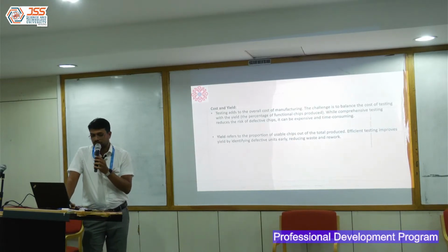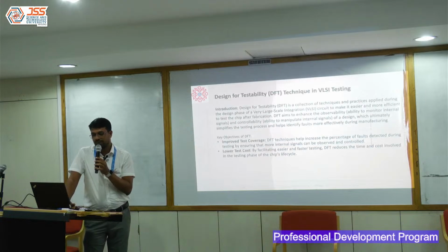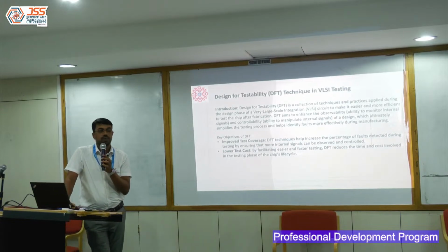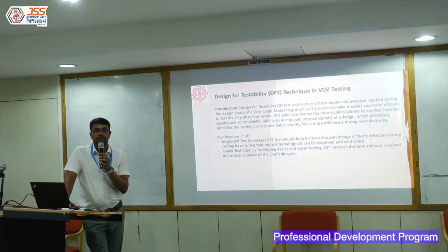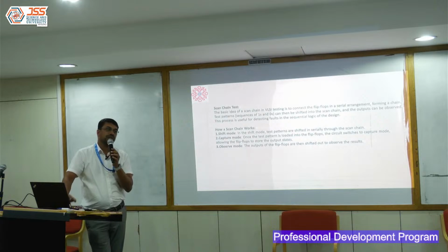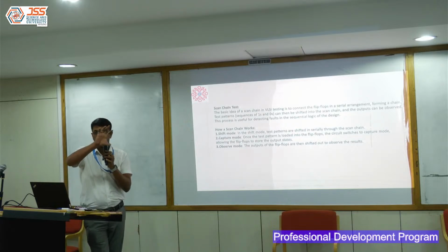I spoke a lot about cost and lead, so I'll skip this. This is the DFT technique which I was talking about, which will help us improve the test coverage. Test coverage means quality and lower cost, because if I can test the chip quickly, it is going to reduce my testing burden. This is the scan chain which I was talking about. I was mentioning that your scan chain is nothing but a huge shift register.